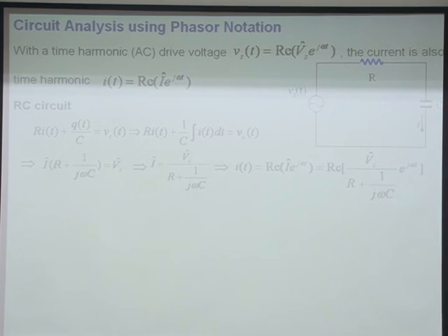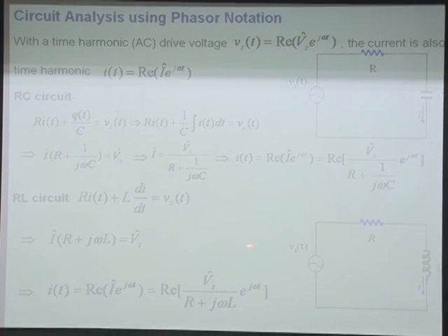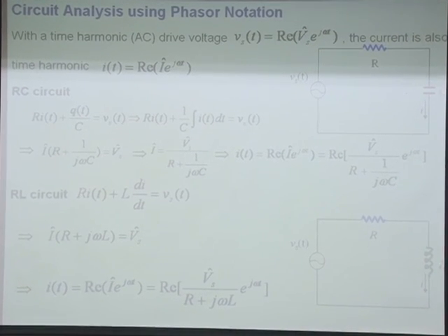The same thing, you also do the same calculation for electromagnetic wave, or transmission line variables. So this is just one very simple but quite powerful example to tell you that in your calculation you can just take out this exponential j omega t, and then finally once you get your answer, you put it back.